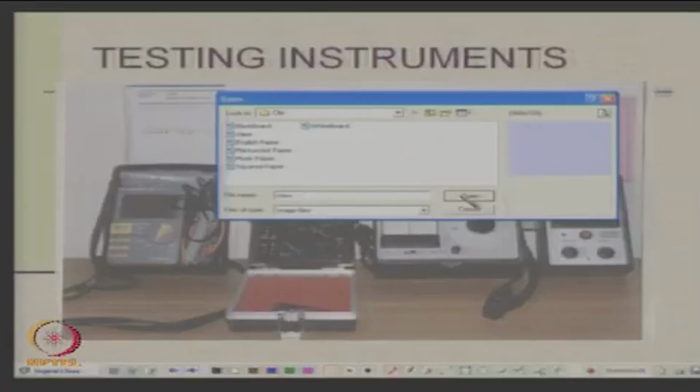Sometimes if you want to test a pump, you need flow meters. So you need to measure speed, linear speed, rotational speed, temperature, frequency, and mechanical quantities. There are several quantities which you need to measure if you want to be accurate.